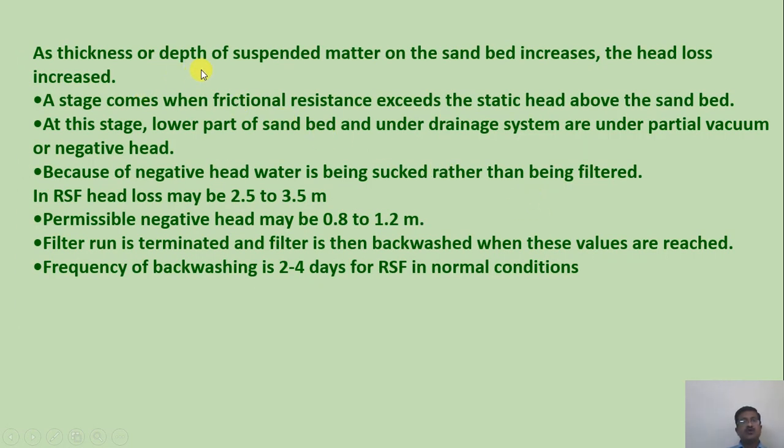As the thickness or depth of suspended matter on the sand bed increases, the head loss increases. A stage comes when frictional resistance exceeds the static head above the sand bed. At this stage, the lower part of the sand bed and under drainage system are under partial vacuum. So it is clear that we will have to take more precautions here. All the steps are very important in the operation of the filters.